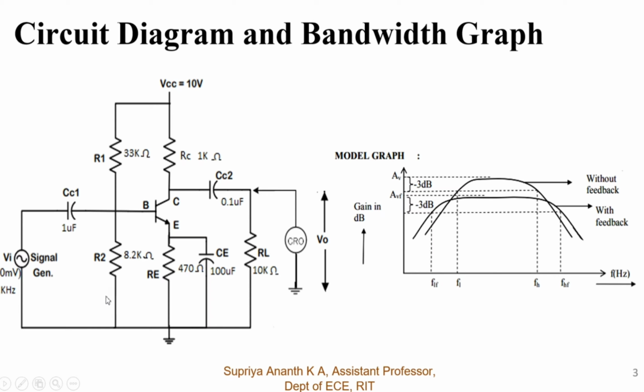So the procedure for this is, initially, you need to give a sinusoidal wave as the input waveform. We need to set up a sinusoidal wave, and before that give the power supply of 10 to 12 volts and record the voltage you get across the oscilloscope. Find the values of the sine wave at the input and then set the sine wave amplitude to 20 millivolts, which is sufficient. So we will get a mid-band frequency.